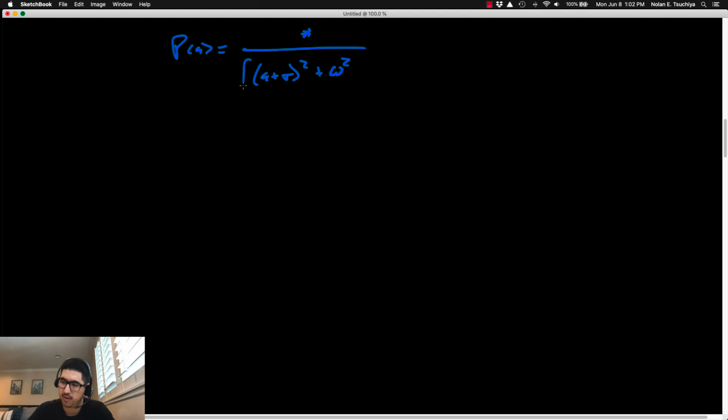Now, if I take that whole denominator and I square it, this is a scenario where you have repeated complex poles. Whatever sigma and omega are, you're going to have a total of 4 poles, and they're going to be 2 repeated pairs at minus sigma plus or minus j omega. That's what this form of a transfer function gives you.